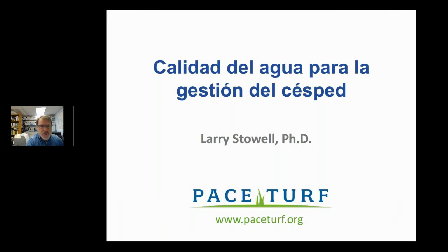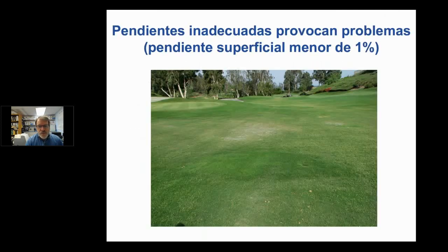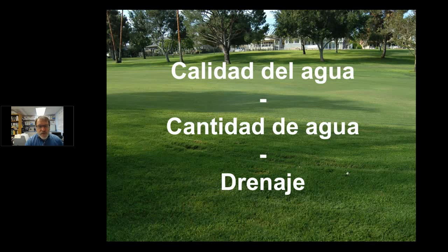The other side effect of top dressing is that it provides a firm surface, and you don't have problems like this where you see rutting due to the soil collapsing when it's wet. If there's sand on top of that, it would not have that big of a problem. So I guess as high as you can get, but certainly at least 80% for distribution uniformity, and a precipitation rate just as low as you can possibly go.